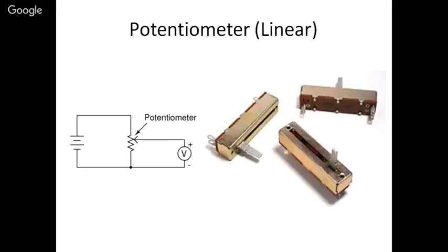So when we say potentiometer, it is a very, very simple yet very useful electrical circuit in which we have simply a resistance, and a voltage source is attached to the resistance so that a current flows. This resistance, you can see, has two terminals. Let us say this is 1 and this is 3.